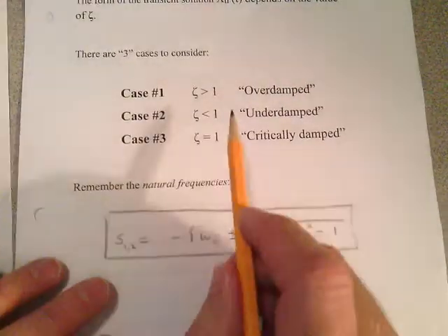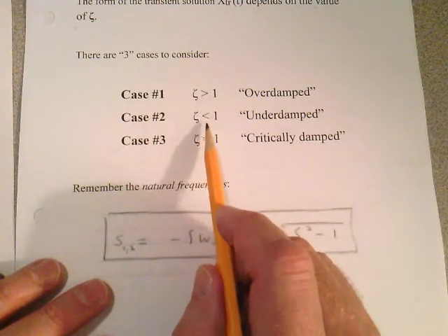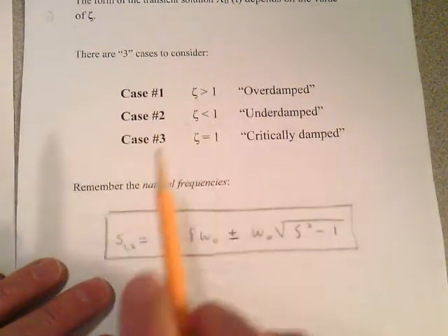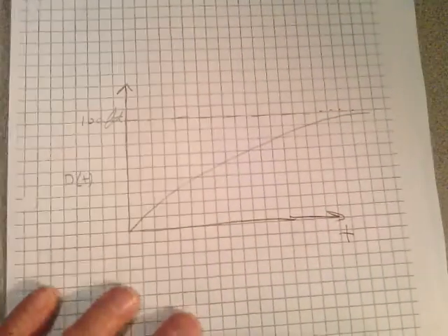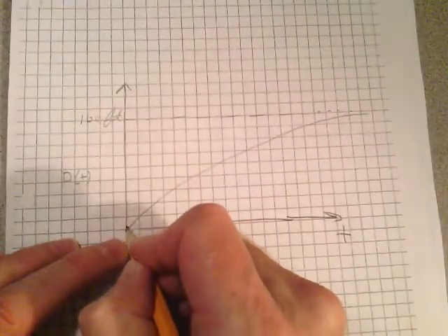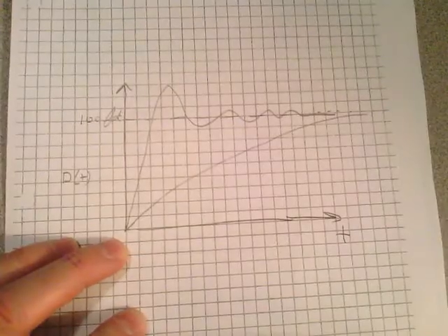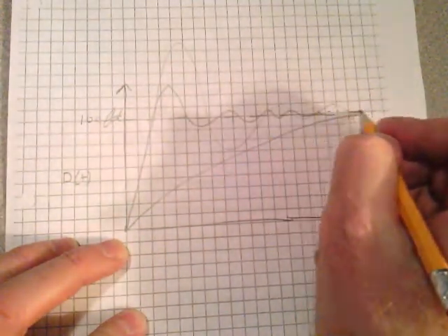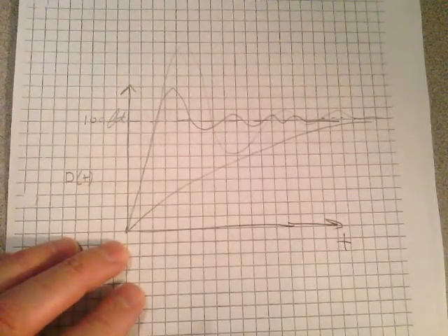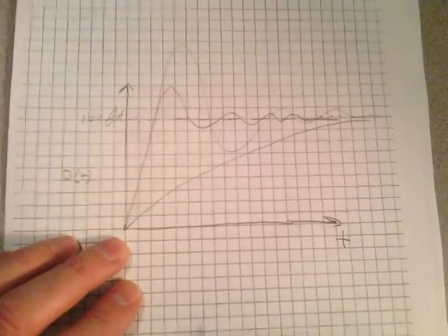Now, you can design that electromechanical system in the elevator so zeta is less than 1. It's 0.7, it's 0.6, or whatever. So you get up there real fast, but your momentum takes you maybe like that, and you get some ringing. Or maybe it's an overshoot that gets really ridiculous, and it goes like that, and it rings out. Well, you've been on elevators like that. I mean, amusement parks would be great.